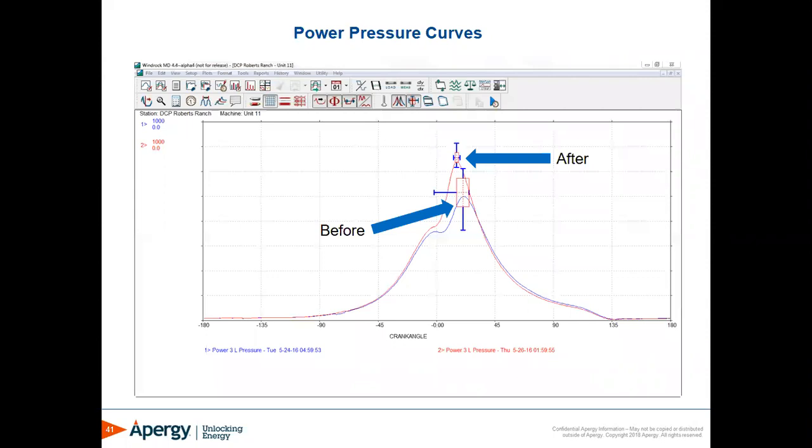The compressor pressure sensors require some recalibration. We suggest recalibrating pressure sensors every 6 months on average. That's simply going into the software, looking at the current pressures compared to what the system's getting and tweaking the calibrations. A 4-throw compressor could be calibrated in 20-30 minutes. It doesn't take very long.